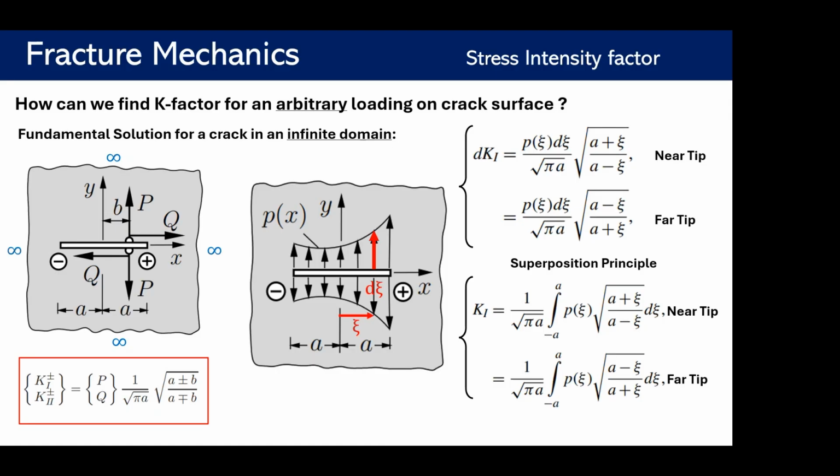For example, if I have a distributed force applied to crack surfaces, I can integrate this fundamental solution over X to find the stress intensity factor.